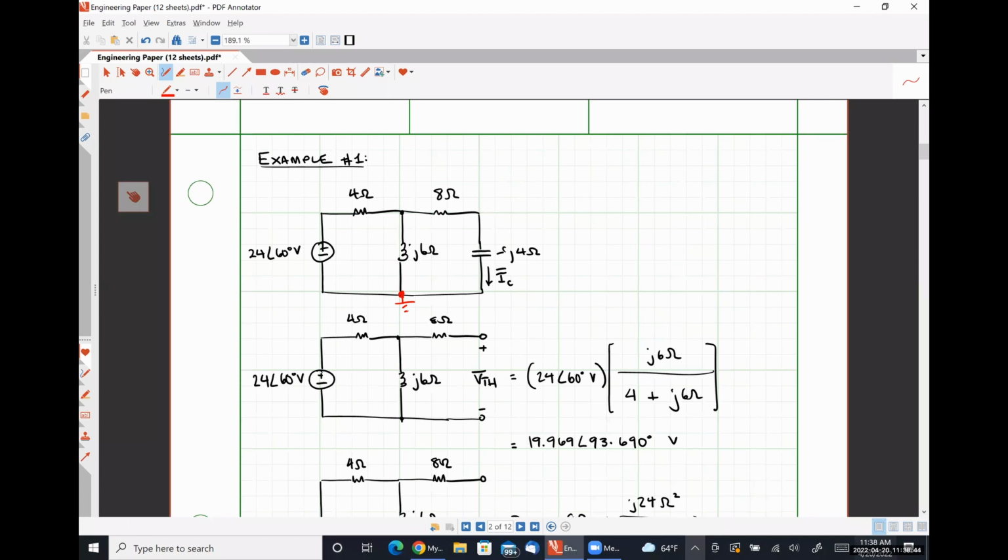So we used Thevenin equivalent circuits, which in turn refreshed our knowledge of voltage division here in this first step, impedance combination in the second step, and then using Ohm's law to wrap things up at the end. We talked about how we could use source transformations and current division, nodal analysis, mesh analysis, KCL, KVL, Ohm's law from the jump. There's really any way that you can think of can be applied to any of these circuits.